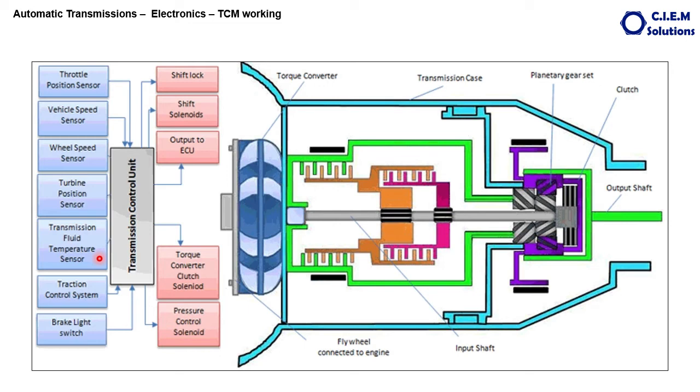The other main important use of having the input from the transmission fluid sensor is that when the temperature increases, the oil viscosity is dropped, so there is a very real possibility the main pressure also drops as the viscosity drops. So in that condition, the TCU can send the signal to the main pressure regulator valve to adjust the main pressure accordingly, in spite of the increase in the temperature or drop in the viscosity. That's why it takes the input from the fluid temperature sensor.